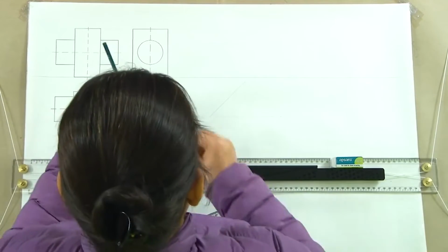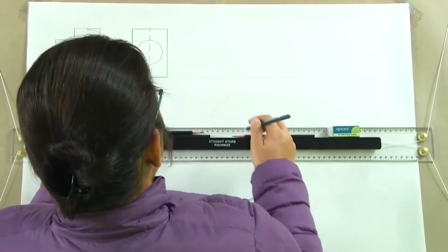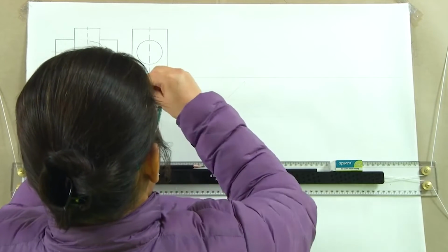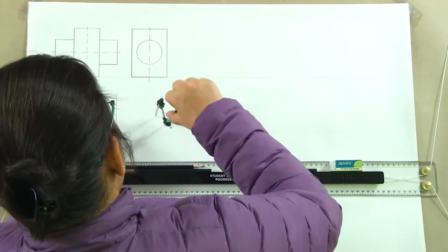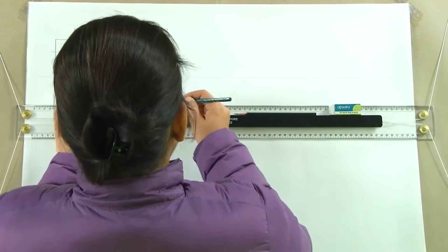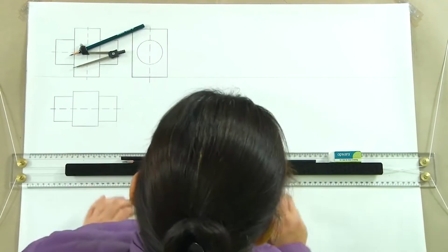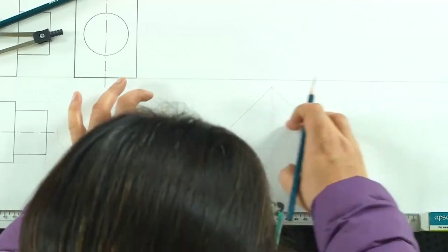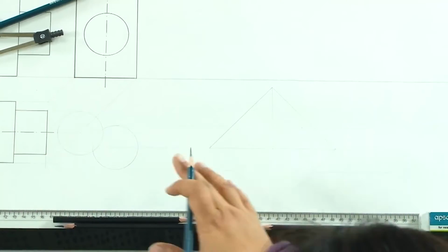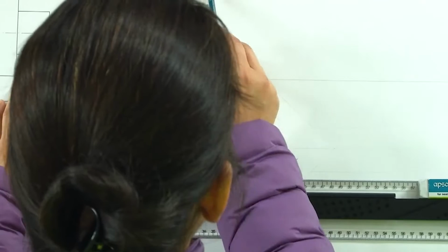Assuming that we have the same size of circular cylinder passing through this square prism, we will just draw a reference here. Since it is parallel to VP, we will be seeing a rectangular shape passing through this. So, what we have is this circular cylinder passing through this. Right now it is assumed to be parallel to both HP and VP, so it is appearing as a straight rectangle, but I am not drawing the ends as of now because it is actually not parallel, and we will draw it once we draw the VP. So, the front view. Now we are taking it up.